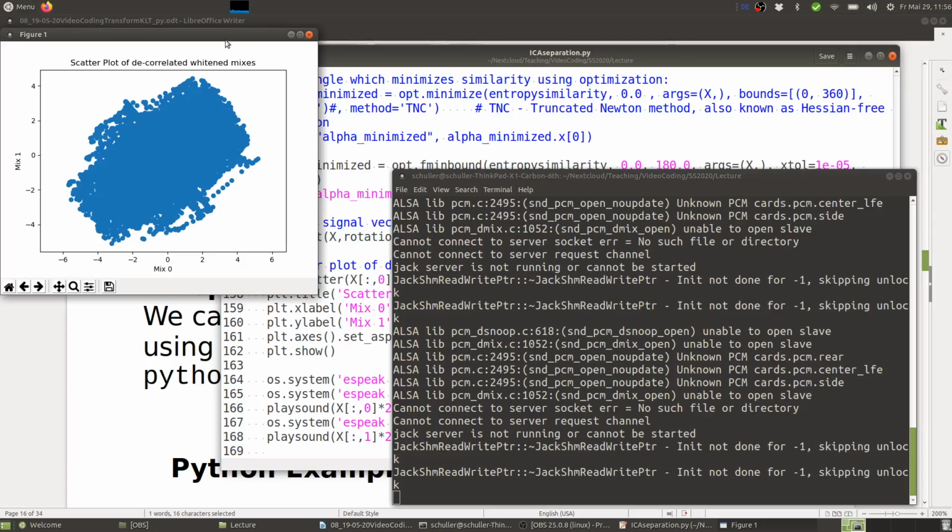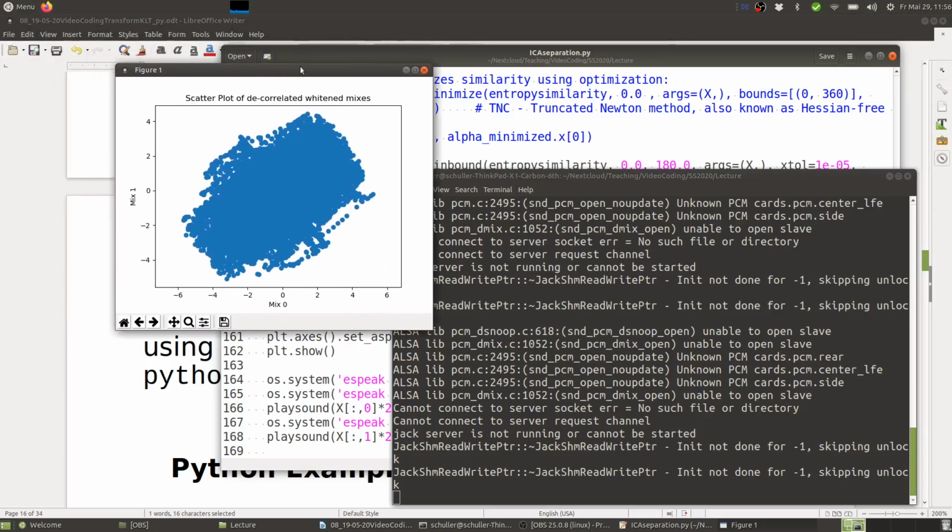So this basically shows the drawbacks of the KLT. One of the assumptions of the KLT, meaning that we have Gaussian distributed subband signals, is violated here, right? And that's why the KLT is not really working in this case. So we have a nice solution, but this nice solution is not really working. That's why we need additional steps now.